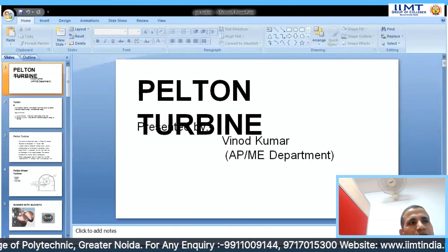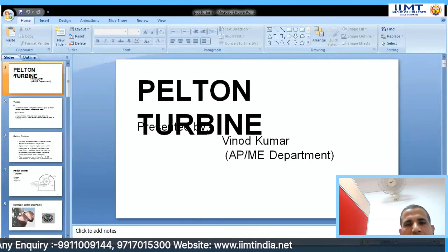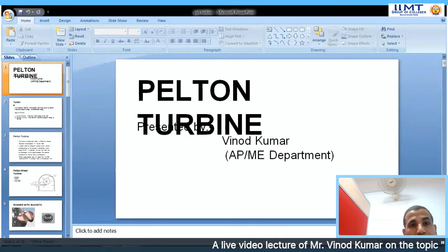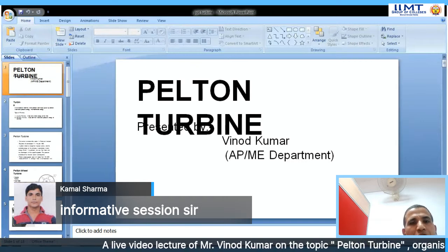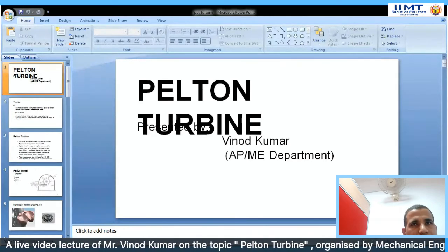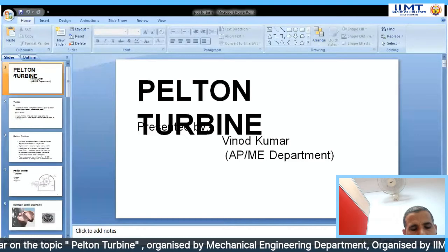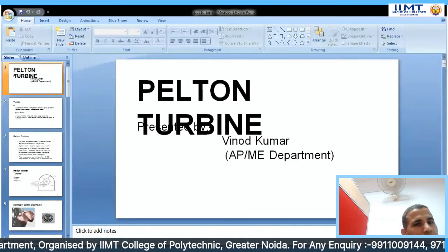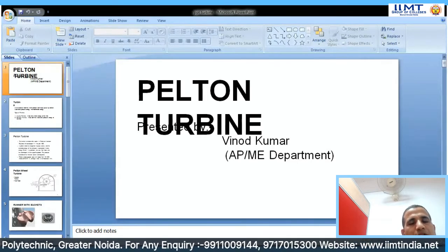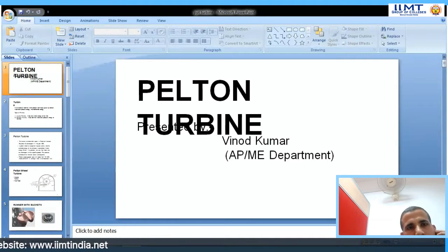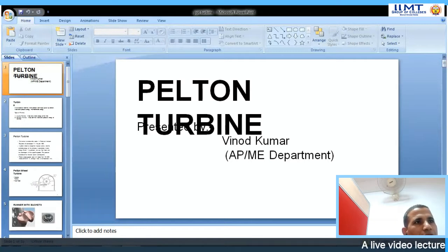Another construction part is the spear head nozzle. This is the part of the regulator of the Pelton wheel turbine. If we push this spear rod to the right hand side, we decrease the discharge of water, and in this way we decrease the speed of the turbine. And if we push this spear rod to the left hand side, then the discharge will increase, and hence the speed of the turbine will also increase. So we can say that the spearhead nozzle is the governing mechanism of the Pelton wheel turbine.